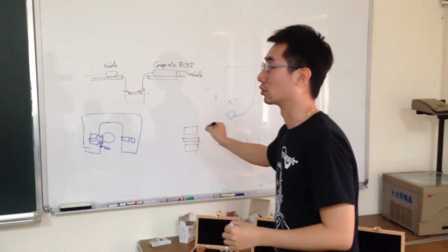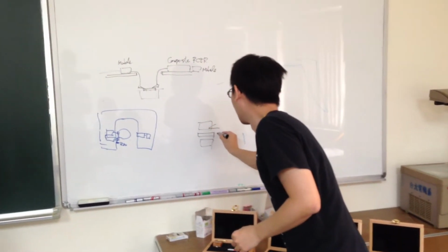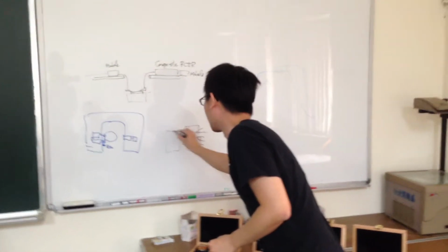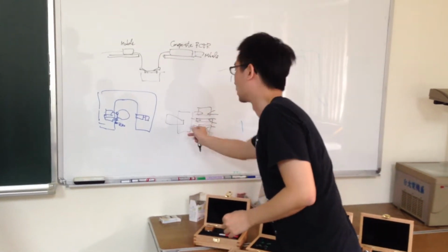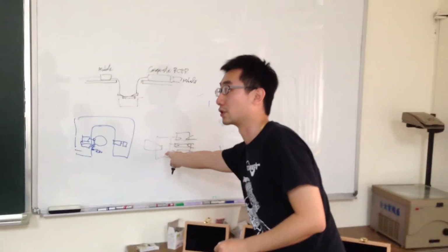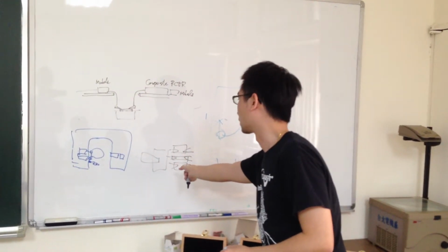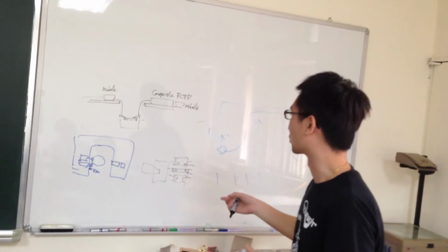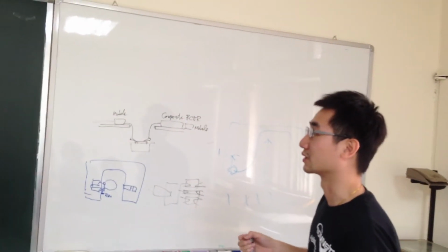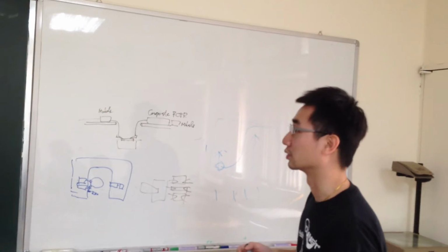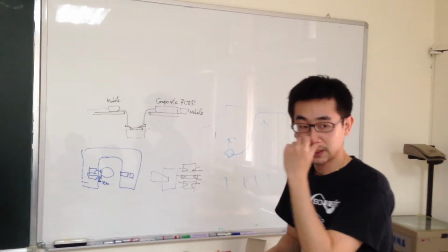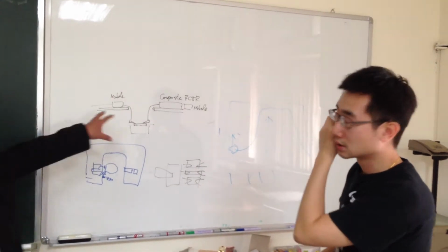And it's almost 50 ohm. Yes. So can we just calibrate by the through and this probe with the terminator, and the loss of this probe will be calibrated, right? Yeah. Yes, I think so. So maybe this method will give more accuracy. That is a good idea.